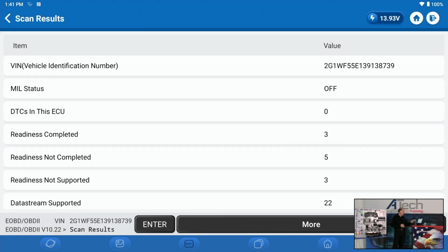Notice I went to the next one, I went down and I went to the J1850. That's with this tester up here. This is not an OBD, this is an OBD2 tester, but it's not a CAN tester, so it's a little bit of a process. And if you're doing your diagnostics and looking at stuff, one of the biggest things you want to do is make sure the VIN is there and it's correct. Some of your scan tools will not pull the VIN. That is mode 9, where we'll pull the VIN number up here.